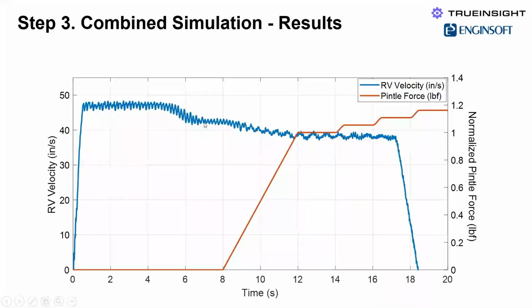Initially, the torque was increased. It kind of flattened out here for a while with the higher torque. You can see some kind of waviness here. And then at some point, things dropped off because that's where the track links were breaking free of the gravel soil.